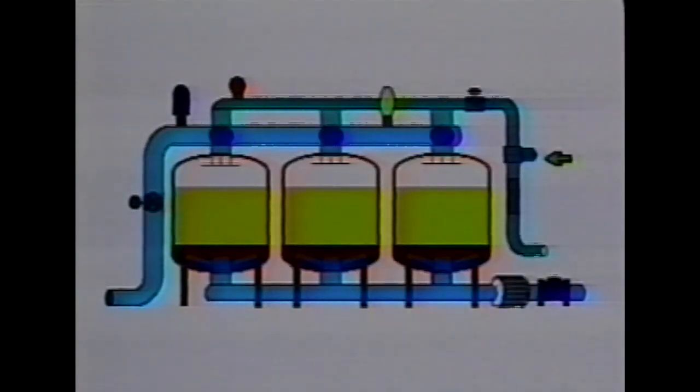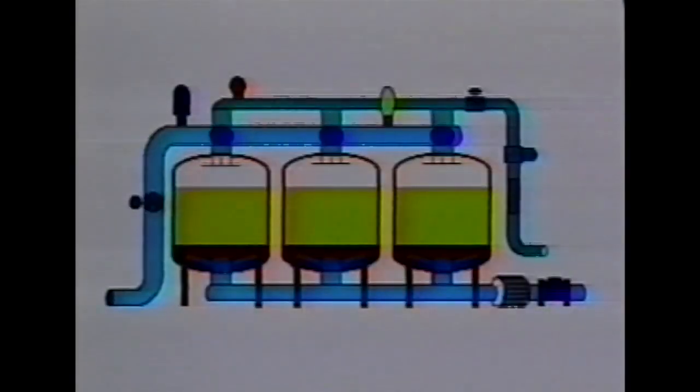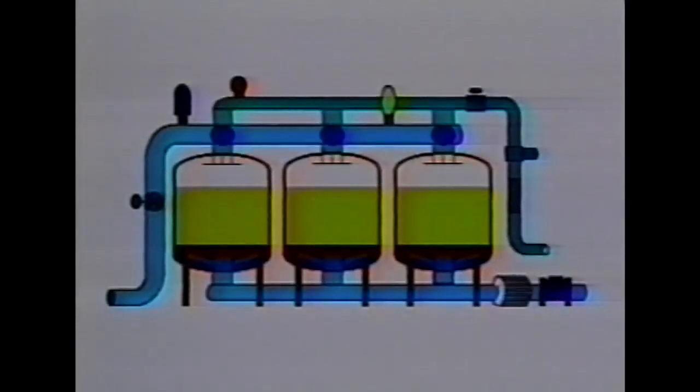There are 2 types of sighting glasses in the backflush line. One is a specially designed sighting and sampling port, which continually passes a portion of the backflush flow through a small attached glass jar, which allows an operator to see if sand is passing by. Another is a section of clear plastic tube, which allows the operator to see if the backflush water is dirty or clean. This tube should be kept covered to protect it from sunlight damage, except during backflushing.